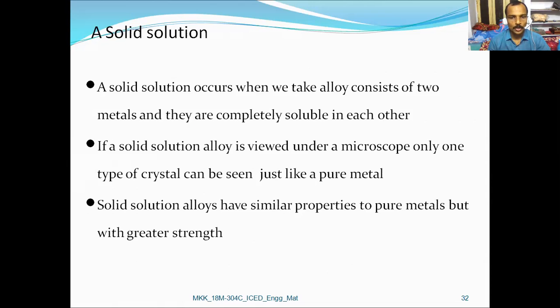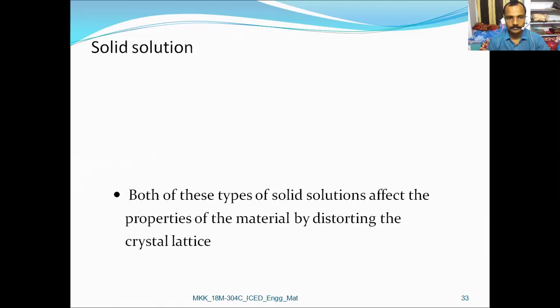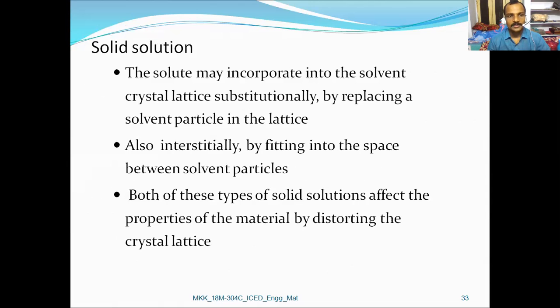Solid solution alloys have similar properties to pure metals, but a solid solution has greater strength compared with the pure metal. A solute may incorporate into the solvent crystal lattice substitutionally by replacing a solvent particle in the lattice.